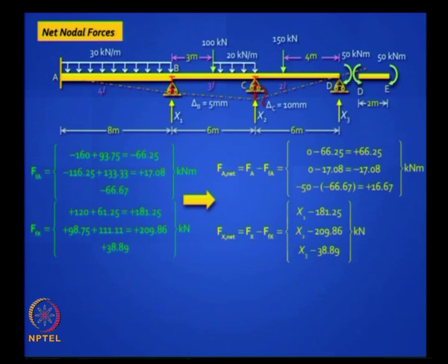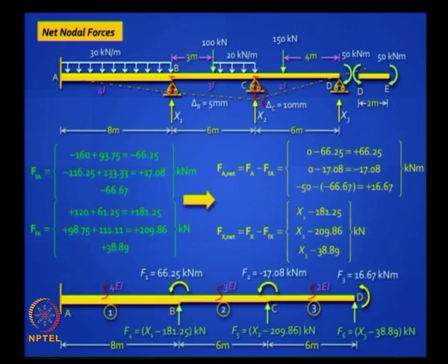Then what is nice to do next? Take a look at those in the diagram, you see how beautifully you have converted all those intermediate loads into equivalent joint loads. That is the power of matrix methods, and you get the same displacements at B, C, D, that is the basis of the equivalent. Is it clear?